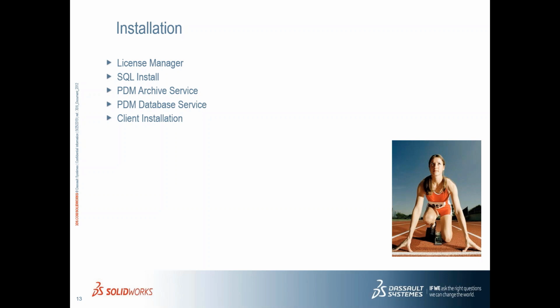And then the fifth thing that's part of that installation process is installing the client software on the client machine. If you're already a SOLIDWORKS user, we would modify your SOLIDWORKS install and include the PDM add-in. If you're not a SOLIDWORKS user, maybe you have guys or gals that need to access PDM and they don't use SOLIDWORKS, we would install what we call a contributor license or a viewer license. That gives them the ability to access PDM without needing a SOLIDWORKS specific license.